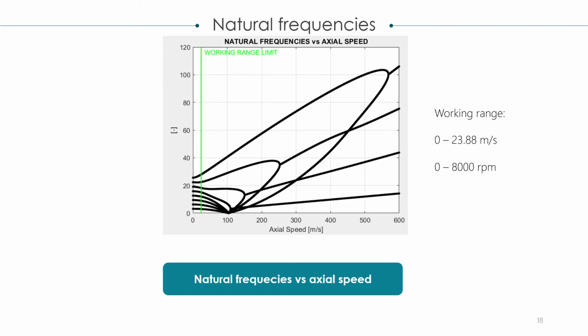In the subcritical area, the natural frequencies, 8 of them because we chose n to be 8, tend to decrease for an increase in actual velocity. The highest two do not share this trait, but this anomaly can be explained by the inherent numerical error produced by our model.